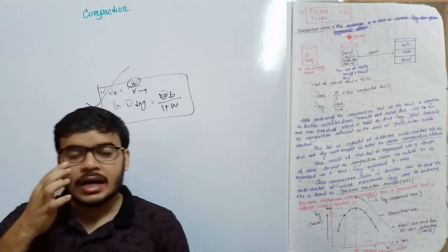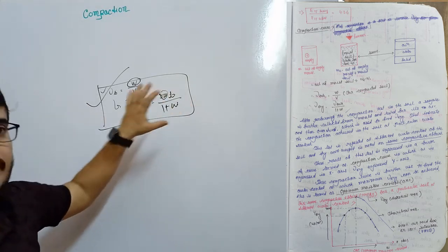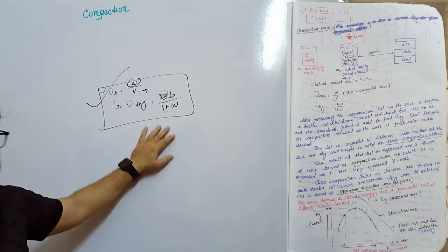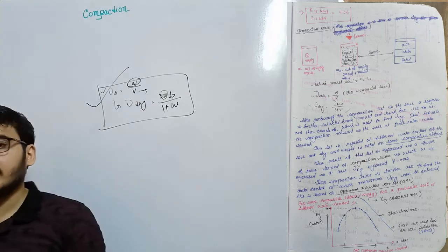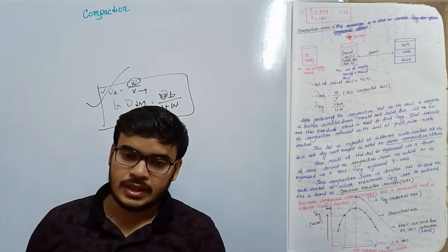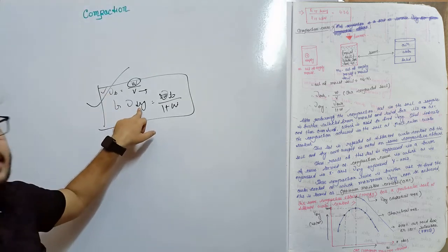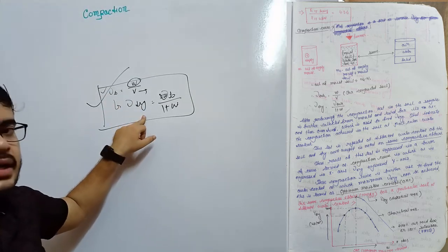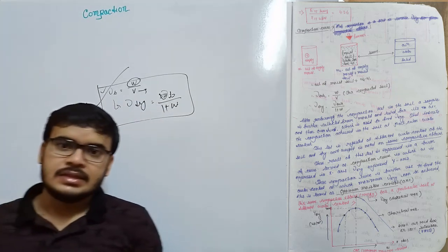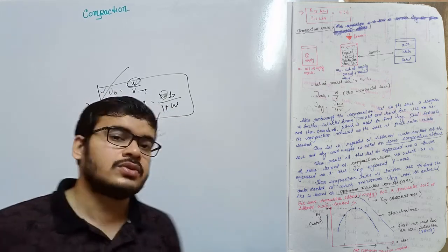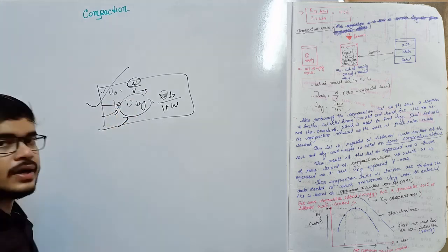As you know, we determine the water content by taking the sample in a container and putting the soil in the oven. Then from the water content value we can convert the bulk unit weight into its dry unit weight, gamma dry. Here, as you already know, compaction is denoted by dry unit weight, so this value is important.